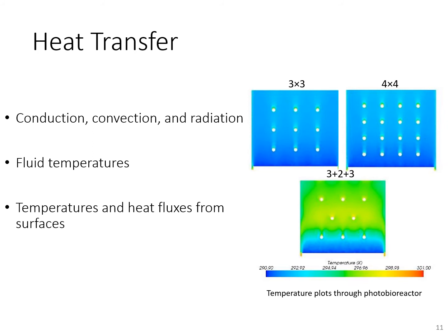In the examples shown here, column photobioreactors with relatively cool carbon dioxide bubbles injected at the bottom of the column were studied with various configurations of light guides protruding through the column, which provide light and heat to further promote photosynthesis of the nearby algae. This study determined that square configurations of these light guides promoted the most consistent temperature throughout the photobioreactor. The staggered array of light guides caused elevated temperatures towards the top of the photobioreactor, potentially inhibiting the growth of algae and drying it out.